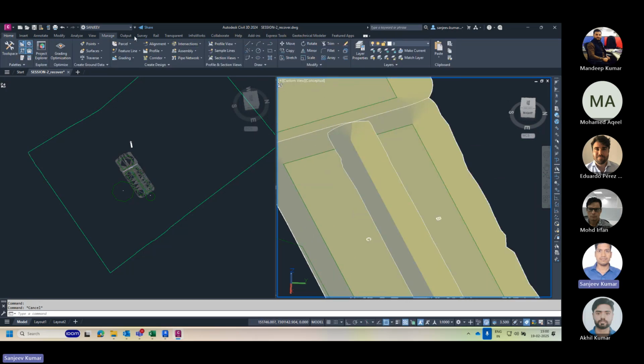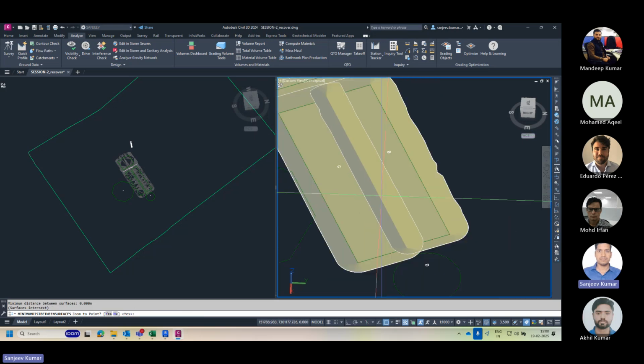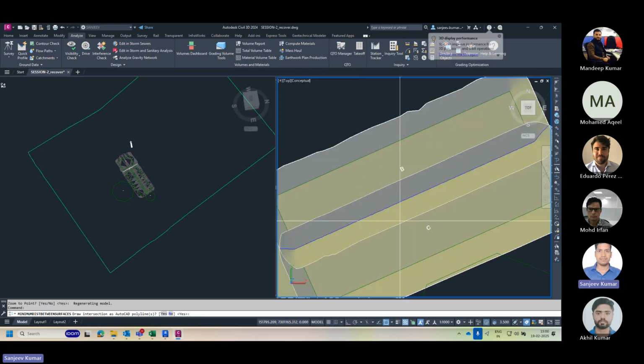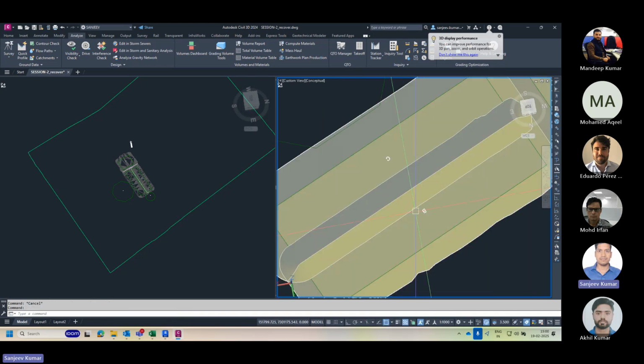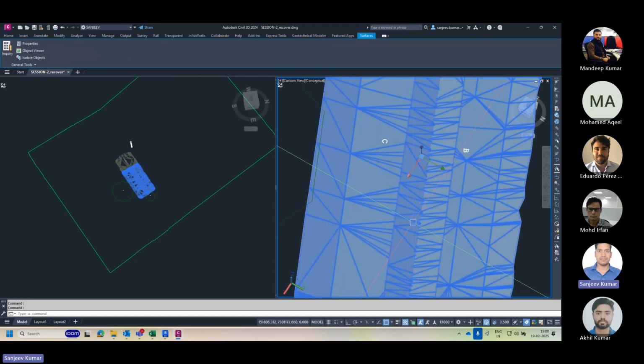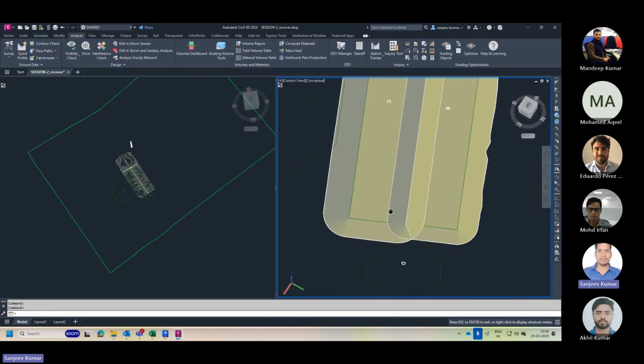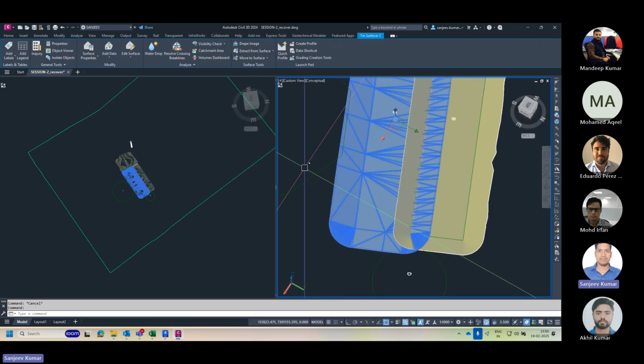We can check this line. This is available in Analyze, Ground Data Analyze, Minimum Distance with two surfaces, and it gives you the exact intersection point and gives you the line. Yes, okay. It is a common break line for both surfaces. So one time we add this point, and again we add the break line.